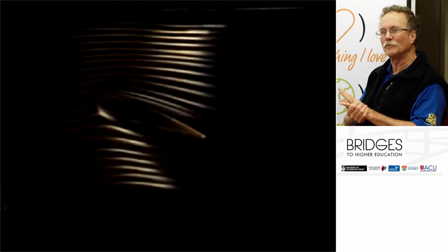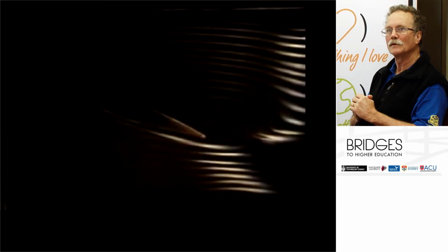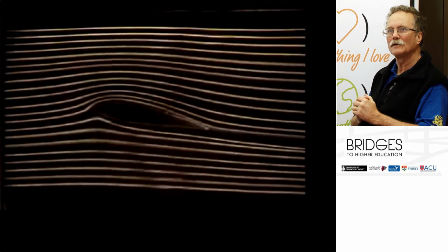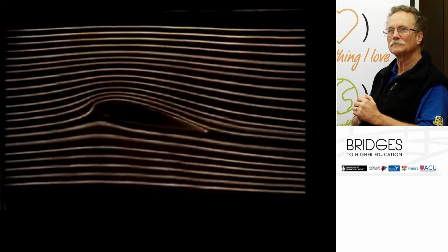And then if we apply the Bernoulli principle, that means that the pressure over the top must be lower. Pressure is proportional to the inverse of velocity squared. The faster you go, the lower the pressure. We'll see the pattern change as we increase angle of attack. So at low angle you get just a residual bit of lift. Higher angle you'll see much more acceleration over the top, much more lift. It's effectively linear.